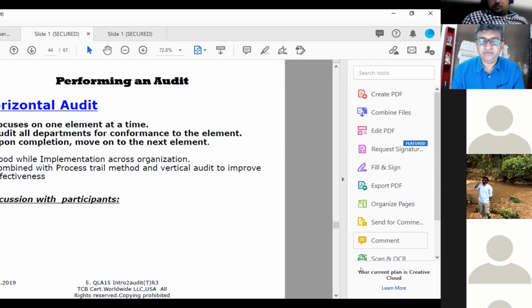But at that point of time, my intention is not to find whether they are really doing it or not. I'm with an open mind asking them, can you please explain your plan for the day? You have done the hydro test. Can you show me the calibration report of your pressure gauge? Many organizations actually issue a gauge issue register because the gauges are very precious items.